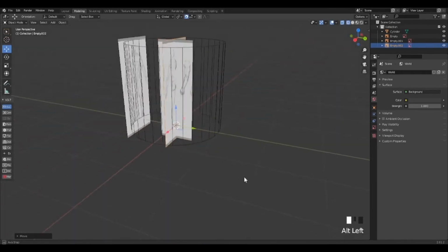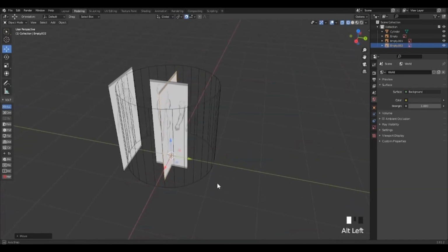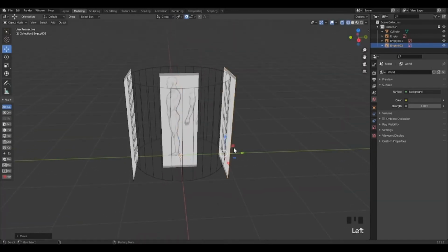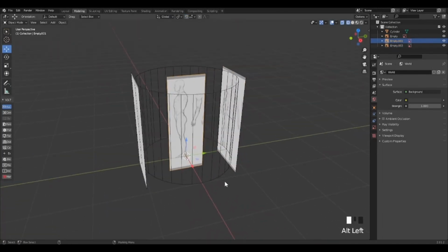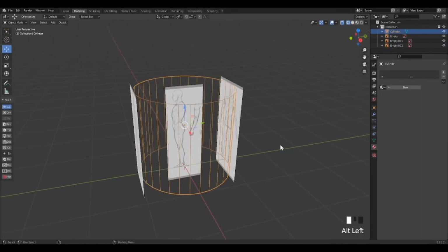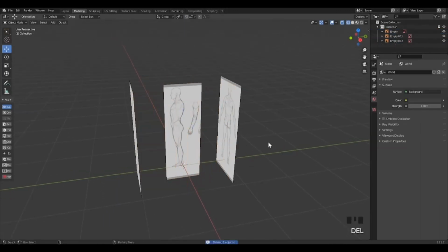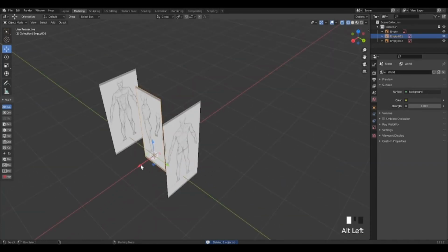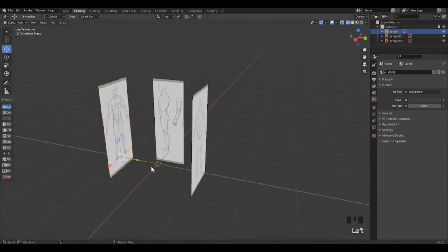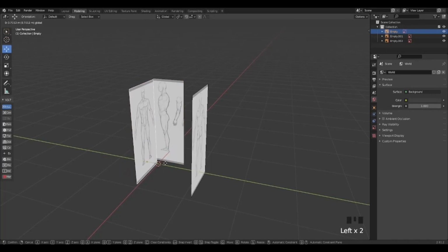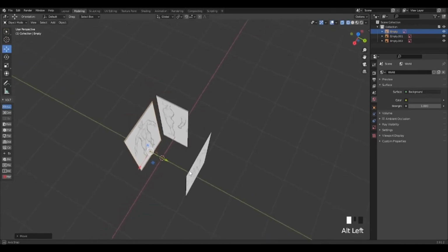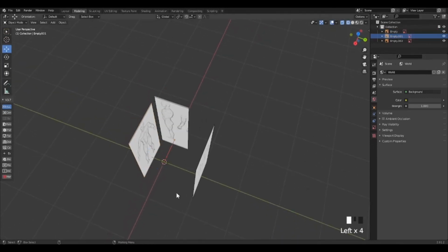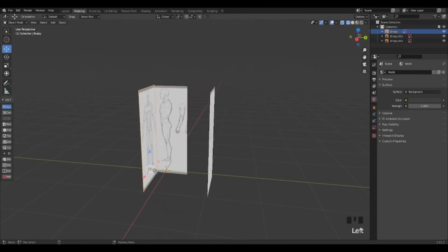All right, great. Now you can see when we go into our perspective view here, we have all of our different reference images. I'm going to turn off grid snapping just so that I can adjust these a little bit more freely. We are finished with our scale since we've already set the height of our references, so we can just delete that. Now I'm going to set these up so that they line up with each other fairly well, and depending on which image you need at what time, you can set them active on and off like this. I'm just going to leave them all active for the time being because we're going to be working with all of them.